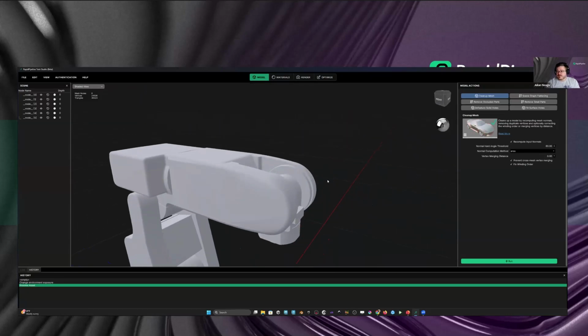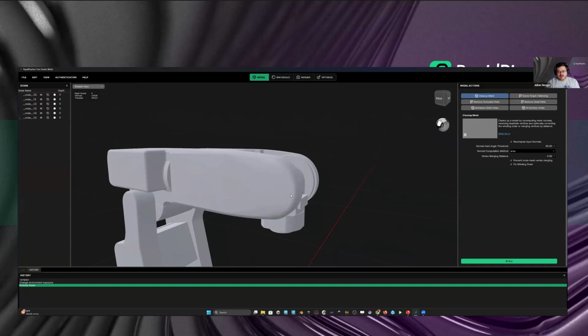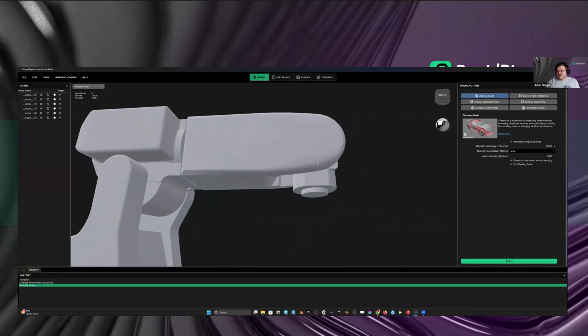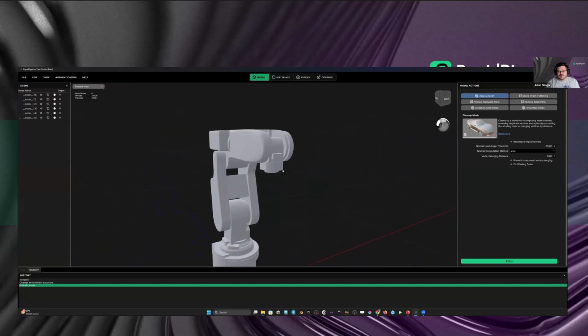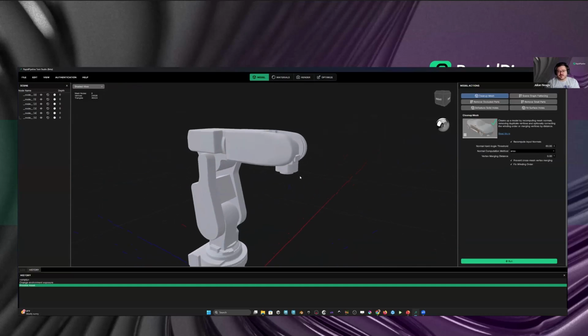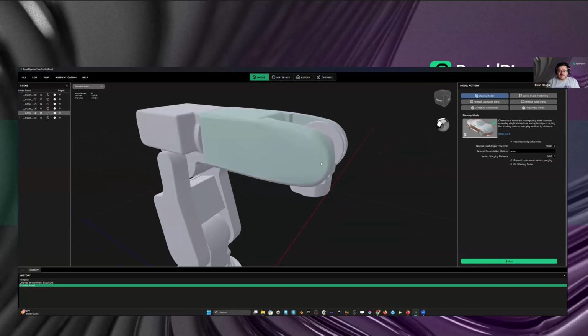But as you can see for CAD models, especially with interesting tessellation paradigms, you really don't get great shading. If you encounter anything like that, and it happens that these normals are stored in the wrong way, or something goes wrong on the file interchange level coming out of a DCC tool, for example, this can happen. To easily fix that, for CAD files we recommend an angle of 30 degrees and the computation method area, for example, and then rerunning this again.